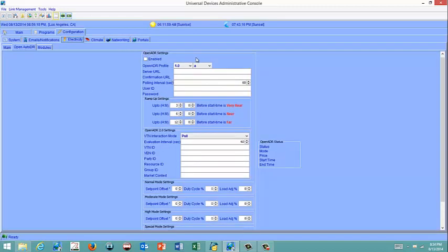Now, this is the setting here, OpenADR settings, and based on what the utility is, you can put their URL for their server in here, put in the username and password for the account, and then you can set up the intervals on when you want to have things turn off, the duty cycle percentage, load adjustment. These would be things for maybe motor loads. Once you've calculated what's going to be turning on and off, then you can have this automatically keep track of that and cycle it. That way you're not shutting everything off, you're not putting a building into a situation where it gets hot really quick. It may be just enough that you need to lower maybe a third of all the thermostats. Well, if you don't want to do all 1/3 for the whole run of the event, you can actually cycle through them. So we have the ability to do that with the ISY.